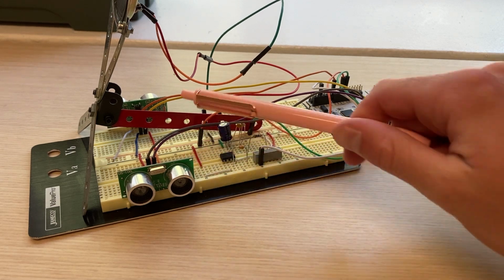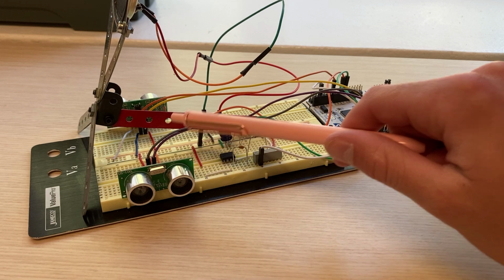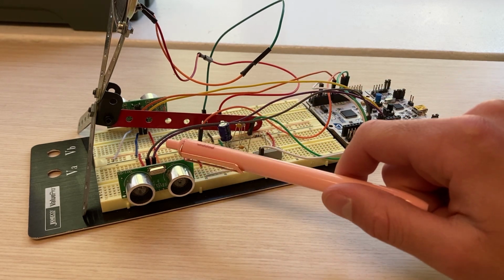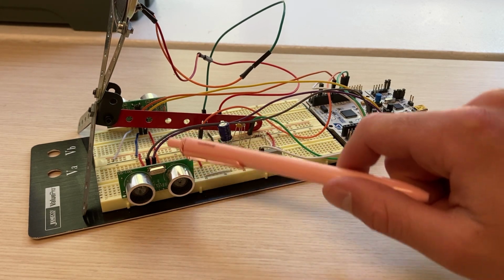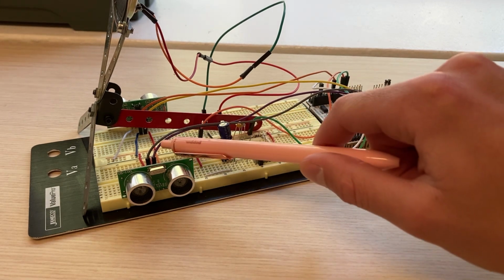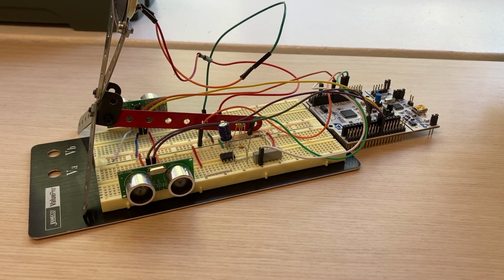Additionally, we have our two ultrasonic sensors. Now, these sensors are a little bit nicer, where we can just send a message through UART, and then these sensors will respond in UART through their RX pin, and they will respond 2 different times with 2 different bytes, and you put those bytes together and you have your distance in millimeters, and we're able to do whatever we need to with that.